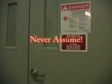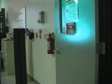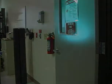Everyone working around lasers may not be safety conscious. Even when they are, accidents still will occur. The following are some tips to minimize the risk of injuries in a laser environment that may or may not be your fault. When entering a room that has a laser, never assume that the laser is off because the outside laser warning light is off. Before opening the door, be mindful of where the laser is and first look away from that direction as you open it. This may give you the time necessary to back away from a stray beam or for the operator to turn off the laser in time.